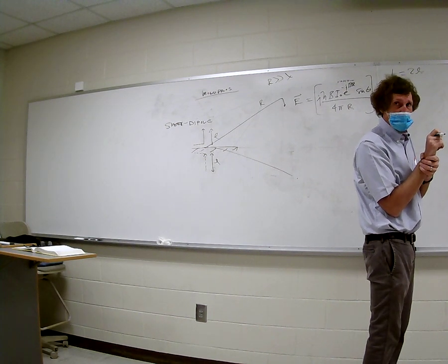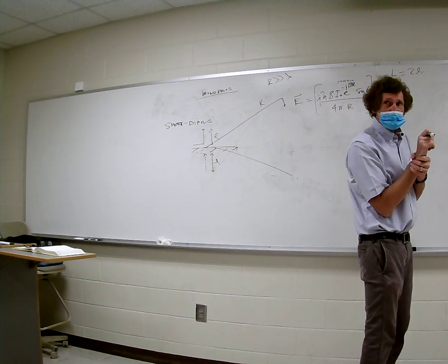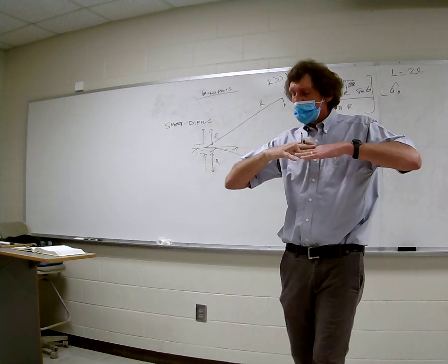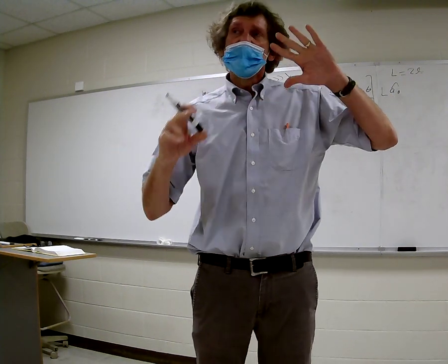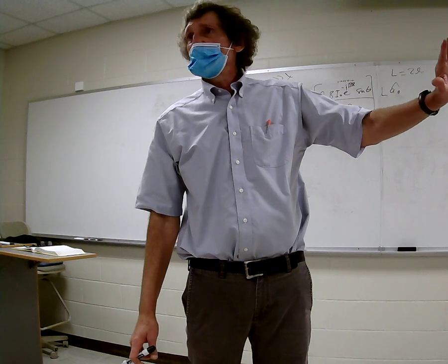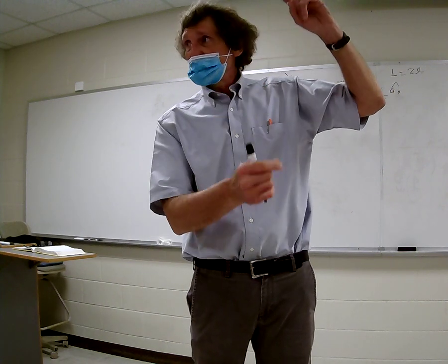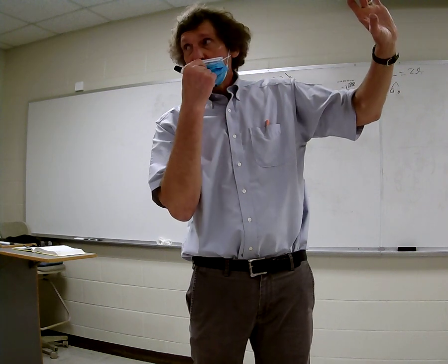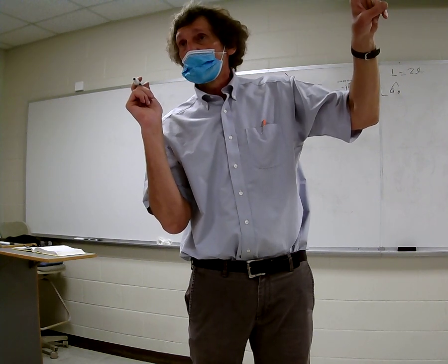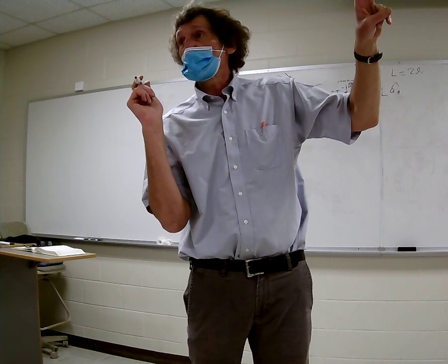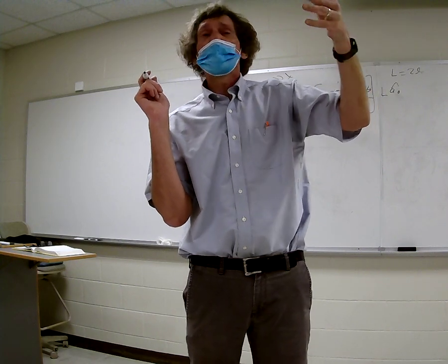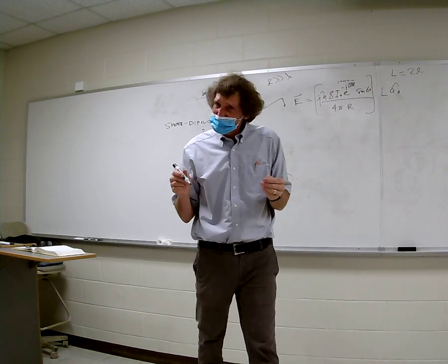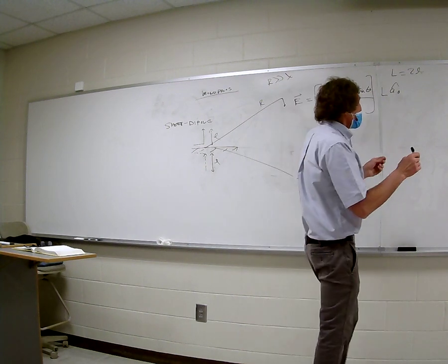Because all the power is radiated only over half the space, you take the gain of the antenna, as if it was a half-wave dipole, or a short dipole adjusted for that length, and multiply by 2, because the power is now just in the upper half plane. Are you with me on this, class? Or directivity. I think I said that in the lecture, didn't I? Okay, good.